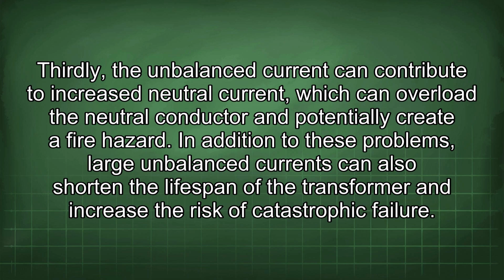Thirdly, the unbalanced current can contribute to increased neutral current, which can overload the neutral conductor and potentially create a fire hazard. In addition to these problems, large unbalanced currents can also shorten the lifespan of the transformer and increase the risk of catastrophic failure.